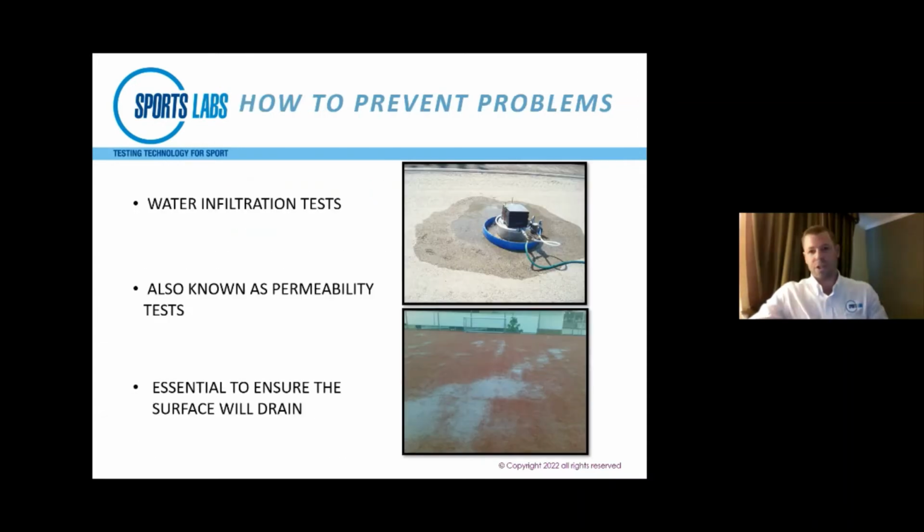So what can we do to prevent these problems? Infiltration testing. This is also called permeability. You might see it called porosity, depending on the spec that you're reading. There's a number of different names for it. All it is, we're verifying that the base actually drains.